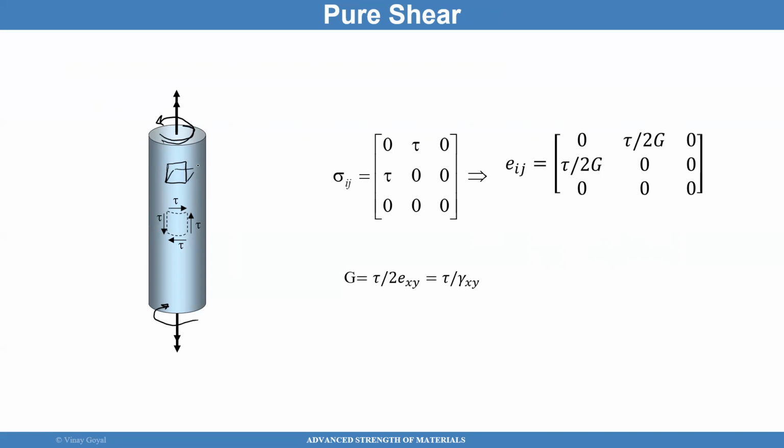I invite you to check it out at home. Maybe take a cylinder of some kind and rubber and then draw lines. You know, I guarantee you that if you drew lines on a rubber and you rotated that cylinder made of rubber, it's going to start rotating like that, and the angles are changing, right? I'm exaggerating, obviously, but that's what shear does. Shear distorts the material. And so if I look at the stress tensor, there's no normal stresses, right? And I'm looking at only shear stresses in the XY plane. So if this is X and that's Y, they're only happening in the XY plane.